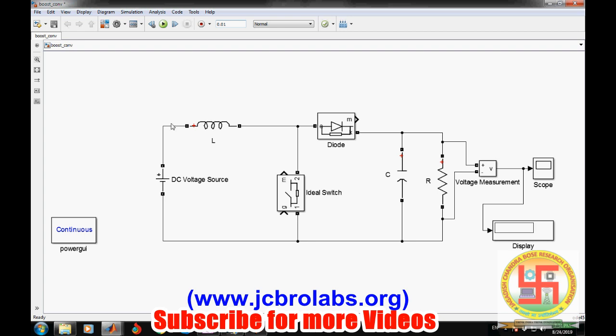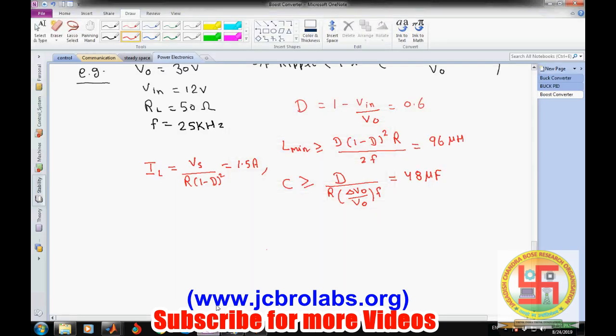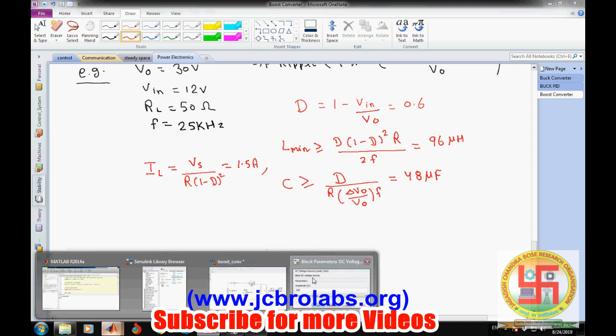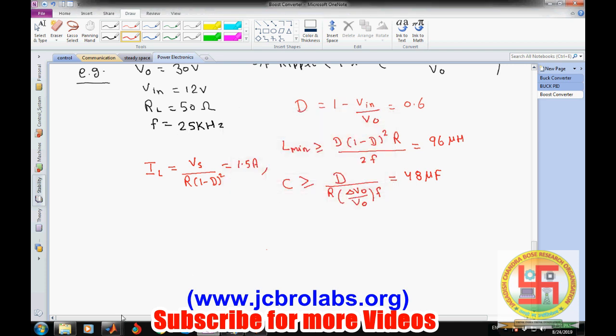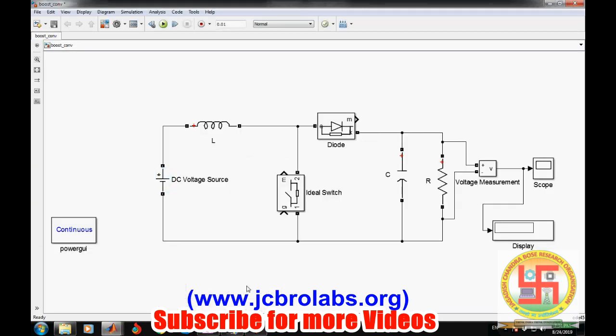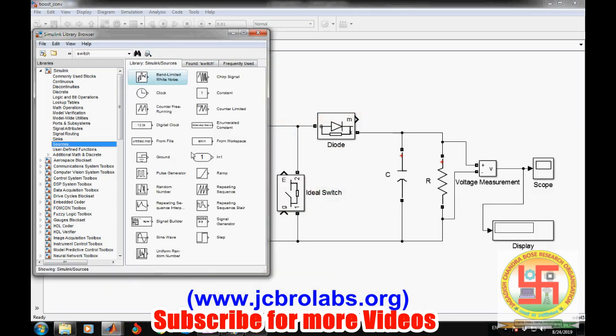Now change the value of this DC voltage. The input voltage was 12 volt, so from the 12 volt power supply we are going to get 30 volt at the output. Apply. Now we need to apply the clock frequency or the switching frequency, and for that we need a square or pulse generator.